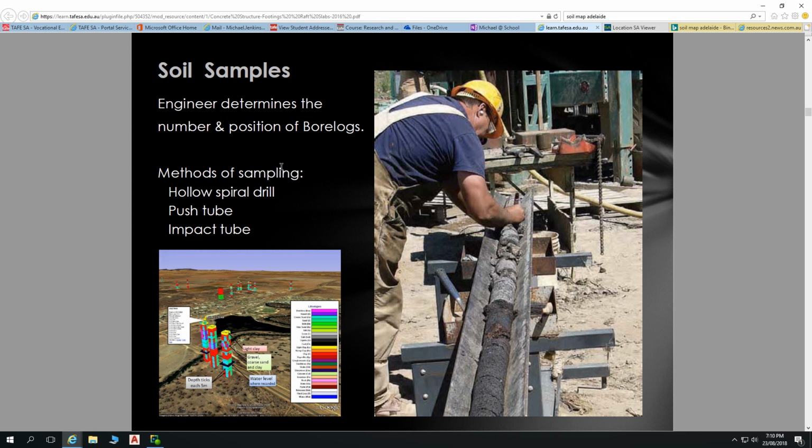Pretty much anything to do with councils, you've got to see it as being council specific. Now, certainly councils sing from the same hymn sheet a lot, so you've got these rules that are the same across councils, but you should never assume. You should never go, all right, yeah, I can do a retaining wall less than 1 metre without council approval. Always check with your council, but typically that's the thing.